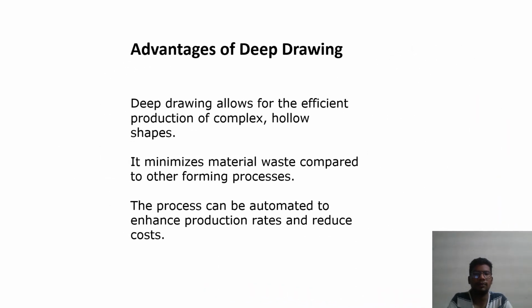Advantages of deep drawing. Deep drawing allows the efficient production of complex hollow shapes. It minimizes material waste compared to other forming processes. The process can be automated to enhance the production rate and reduce the cost.